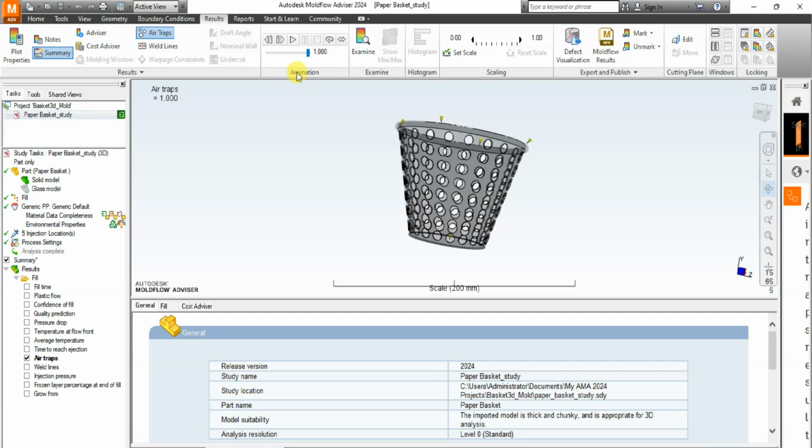In very, very rare cases, the compression increases the temperature to a level that causes plastic to degrade or burn ultimately. So these are things that you need to put into consideration. Now, other things you should also note here is that air traps are often due to converging flow fronts caused by racetrack or hesitation effects, like I previously said, or by non-uniform or non-linear flow patterns.